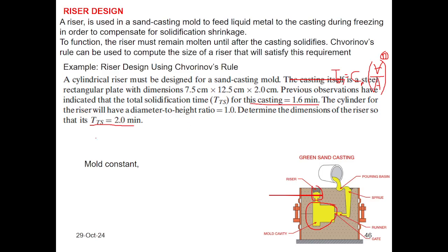That is okay. So although the material in the mold cavity turns back to its solid phase, the riser can still have metal in liquid phase, so it can supply the material while the casting material is shrinking.